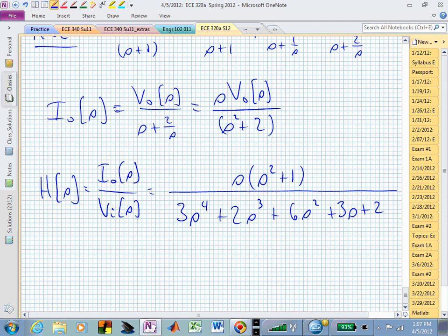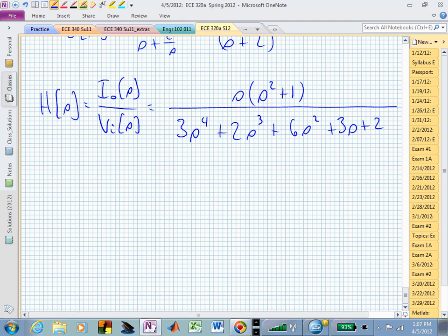And the denominator is a little bit more ugly, but you can factor that if you wanted to. And it ends up being, they're all 4 in the left half plane. They're not too far into the left half plane, but they're at minus 0.318 plus and minus j0.57 and minus 0.015 plus and minus j1.245. I'm sure that was understood.